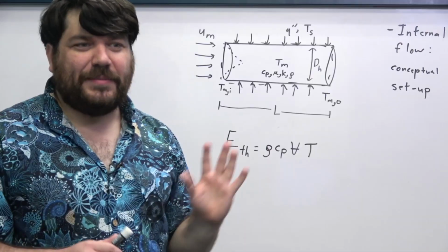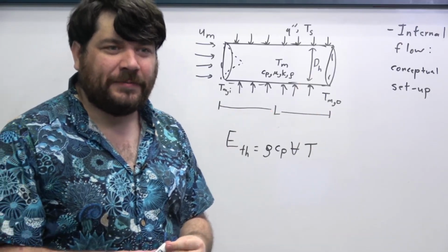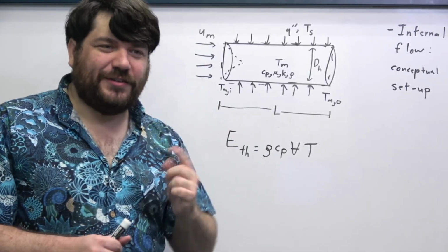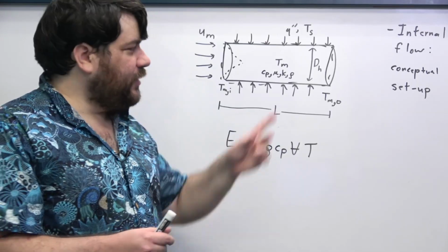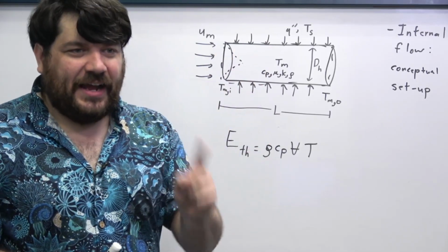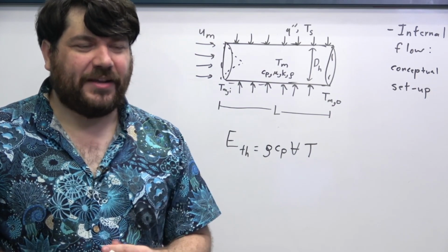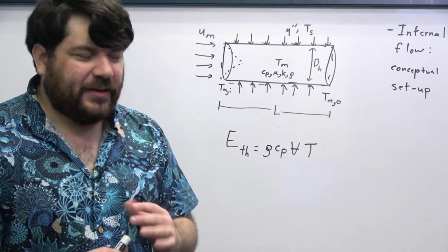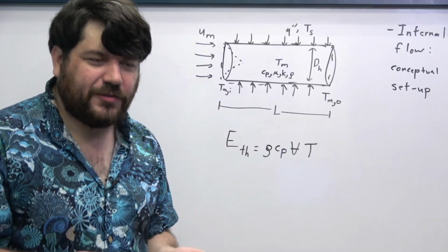Once again, because the matter has speed, it moves and takes its thermal energy with it. And so it turns out that we can't just consider the thermal energy transfers occurring in this region of space that happen because of temperature imbalances. We have this other mechanism, usually called thermal advection, this other mechanism of moving energy in or out of this region, of this control volume.